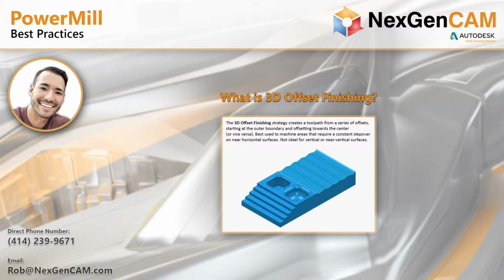This part that I created below, you can see it's on a wavy area. I created those. If you're into motorcycles or dirt biking, we can call those whoops. So we have those right there. I actually have a boundary around those surfaces, and it's creating a 3D offset finishing starting from the outside and offsetting in with a constant step over. Just remember that this is not ideal for vertical or near vertical surfaces. This is actually best for near horizontal or horizontal surfaces. I would not compare it to offset flat finishing, but you can use this on complete flat surfaces. So just keep that in mind.